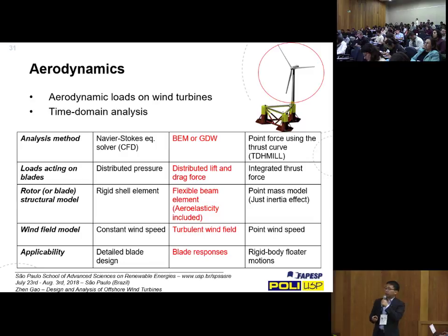I will not go into details very much here, just give you some overview, and we focus very much on this global response analysis. And of course, you have different levels of detail or fidelity for aerodynamic analysis. We do not really use CFD for global response analysis because it's time consuming, and we have to cover different load cases. So basically, we use blade element momentum theory for aerodynamic loads,